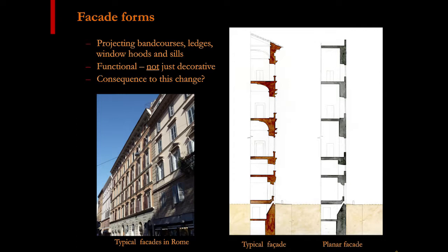Well, it is. The way these walls work, the technical term would be load-bearing mass masonry walls. You have very thick load-bearing walls, which work structurally. A lot of these walls are 2 or 3 feet thick, solid masonry. And that works really well for carrying all the gravity loads of the floors down to the ground.